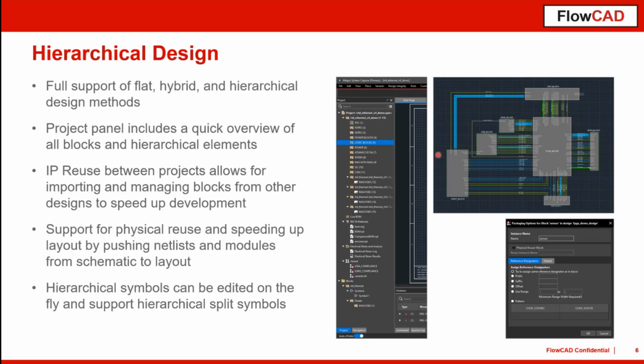Good. So hierarchical design. For sure, System Capture offers the possibility for hierarchical design. You can import blocks from other projects. I mean, this is a basic feature for a modern schematic entry tool. You can also use the full-blown flow with the physical design reuse. As soon as you have Allegro, you can define modules in Allegro, connect these modules to a block inside of the front end, inside of System Capture, and then have a full-blown design reuse flow in the end. So this is also a possibility the tool is offering here.